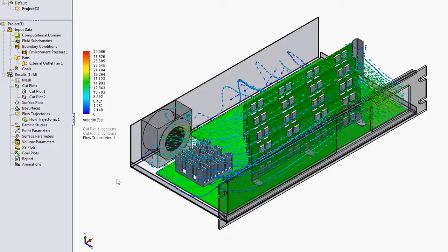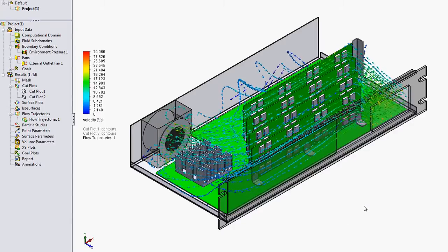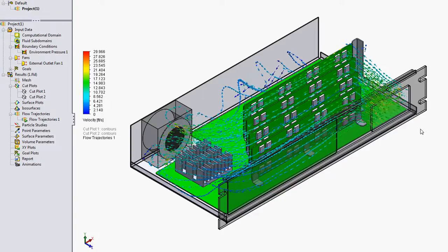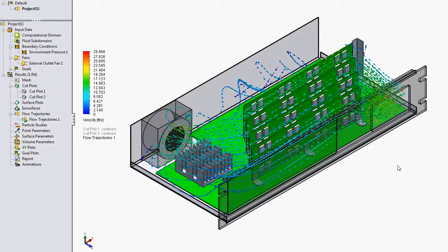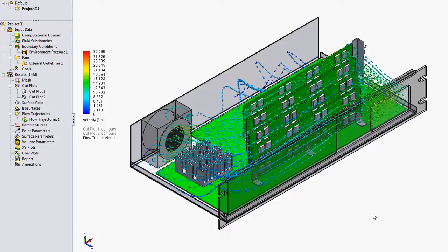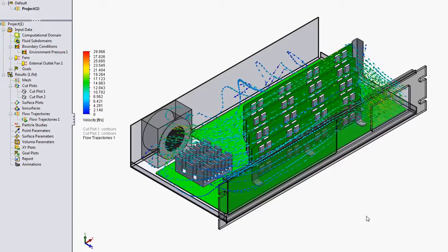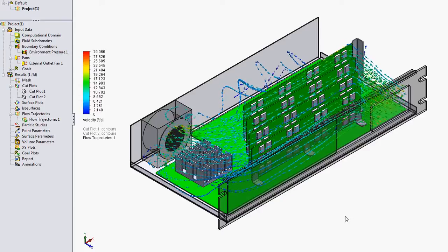So what you'll see is actually, in a full analysis, I wouldn't have the fan selected right away. Basically, what we do is set the intake at atmospheric pressure, and then vary the exit pressure over here. Just basically vary that over the anticipated CFM range for the fan that you're going to be selecting, or for at least a group of fans that you have under consideration.